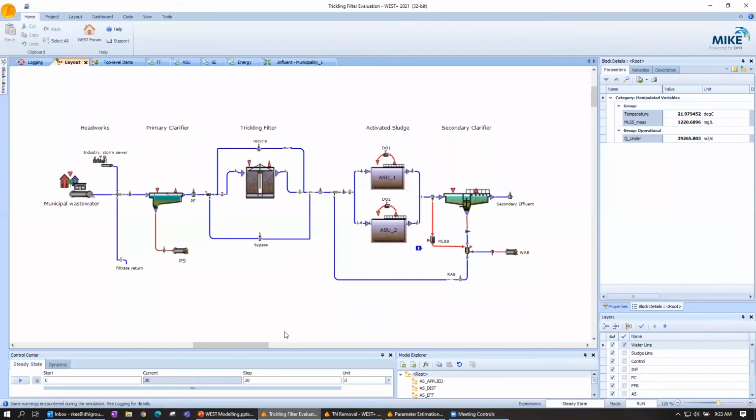So let's make our hypothesis. If you remember, it's an if-then-because statement, or that's how I was taught it at least. And the simplest way in this case, because I know I want to take out more total nitrogen, or at least some ammonia, if I increase SRT, presumably by modifying this MLSS controller, which will just reduce the wasting rate, then I will enable nitrifiers to grow and nitrify.